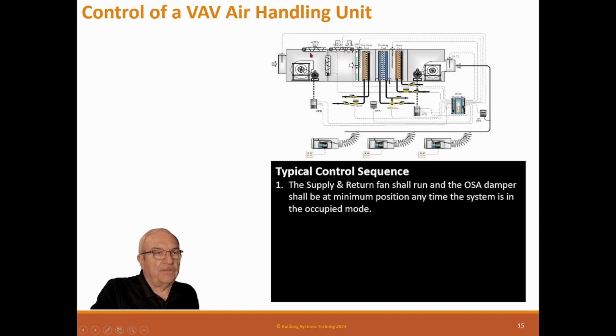So this unit is a little different. It has a full economizer, but it also has a minimum outside air damper there to provide flow when we just need ventilation air. The reason is this is a big unit. These dampers can be very, very large, and they can leak more than your minimum ventilation. They're called low leak dampers, but that's in contrast to a standard damper that you can actually see through. So these have a minimum, and they normally have a flow meter on it, and that allows us to keep this minimum CFM all the time. Because remember, this is a VAV, and as these fans change, there's a possibility this pressure could change, and then we have less air here, so this damper may have to open up as it slows down because the ventilation air is a constant.